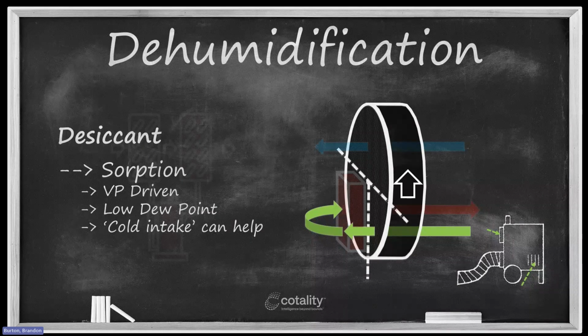Now what's kind of cool about a desiccant is how energy efficient certain types are. The one on my screen here is what we call a purge style, and this green arrow that is being used to cool the rotor down, that air is picking up heat. So we use that heat before we go into the heater to get superheated to bake the rotor dry, right? Kind of a cool efficiency there in engineering. So with all of that said, with this operation of a desiccant dehumidifier, when would I use one and how would I use one? A couple of notes here.